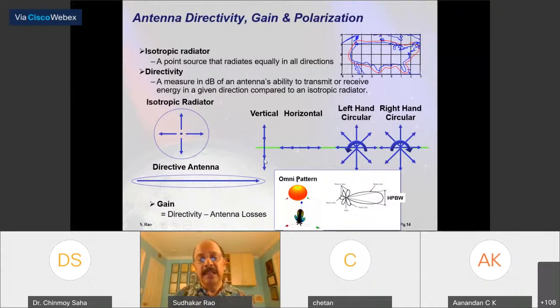Vertical polarization is a bit different from other definitions. For satellite applications, at, say, CONUS within the US, if the E field vector is along north-south, then it's called vertical polarization. If the electric field vector is along east-west, it's horizontal polarization.